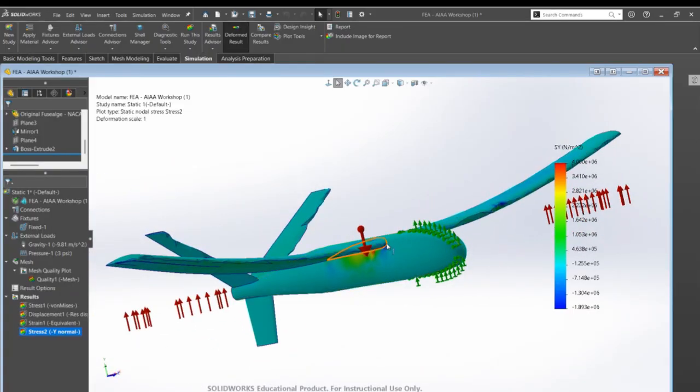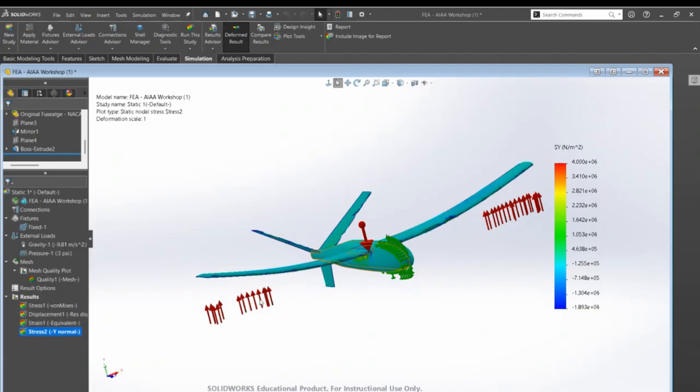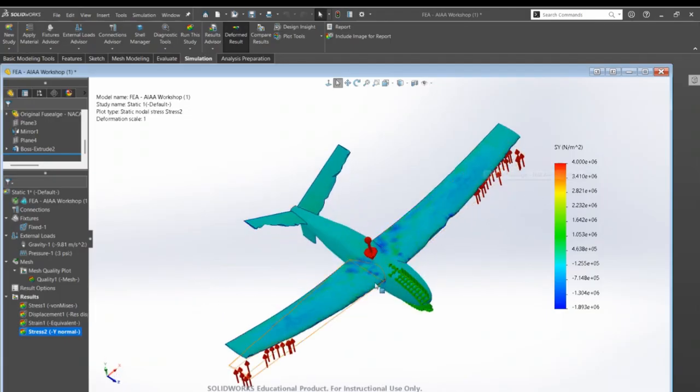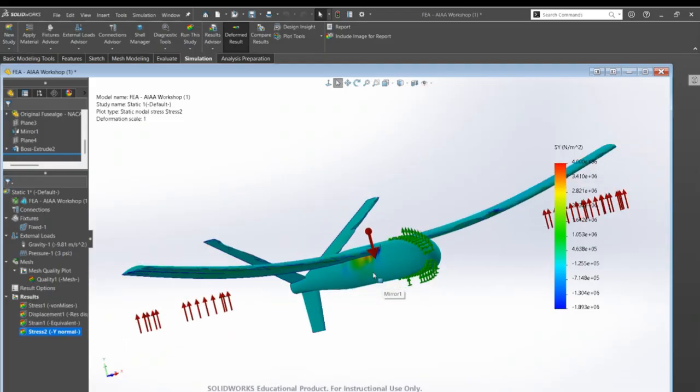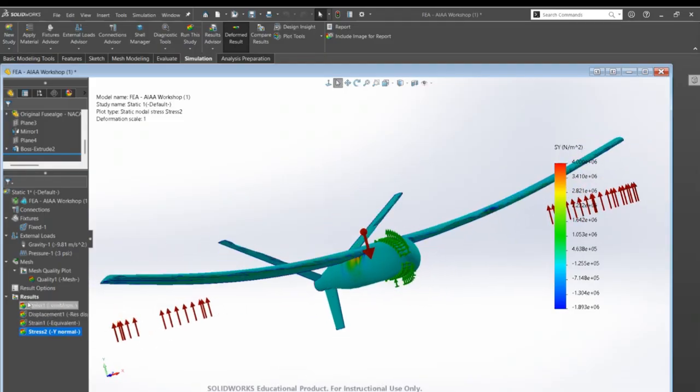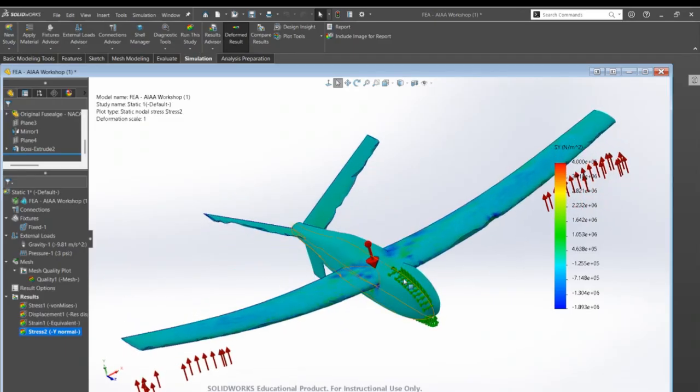Also, another thing that this study shows you is that you could probably use some spars. In our design, we're going to have long carbon fiber tubes throughout the entire wingspan that would mitigate this force, hopefully. So this study is not taking into account the orientation of how you print the part. Correct, it doesn't. This model is assuming an entirely solid block of plastic. Our actual design is very hollow and very thin too, we're talking very thin walls.